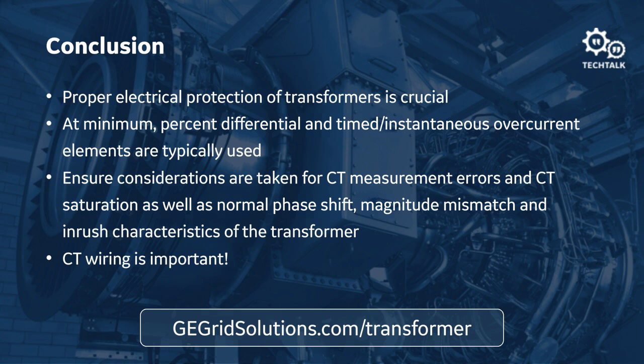All right, a couple more questions. What's the maximum magnitude mismatch factor I can have between the high side and low side and still have the relay do magnitude compensation? For the UR, the maximum is 32. For the 845, it's 20.